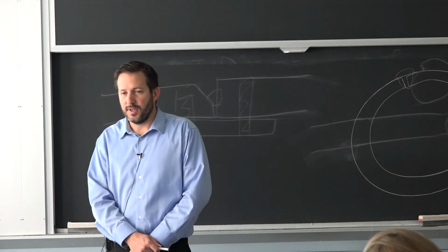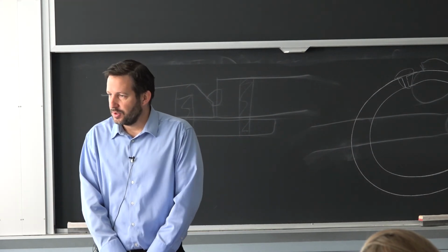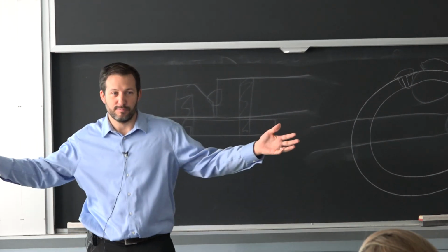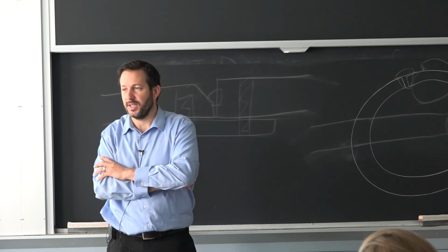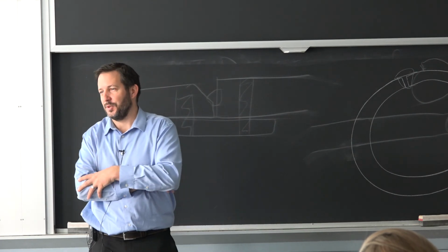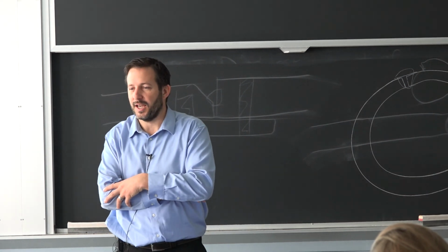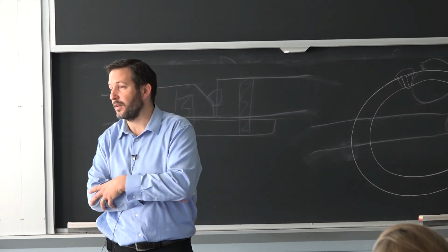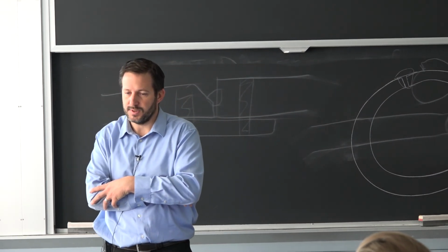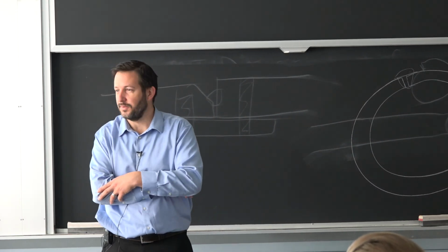And a lot of times it's just because the construction standard changed. So these days when they put on new pipelines, they have a lot of extensive requirements they have to meet for material testing, including cracking resistance and all that. But those things didn't even exist. You know, we're talking about the Charpy. So the Charpy existed, but the other processes of looking at crack propagation were just not there yet. And just a general expectation in terms of reliability was different. It's not clear that people were thinking these things were going to be in the ground for 40, 50, 60 years.